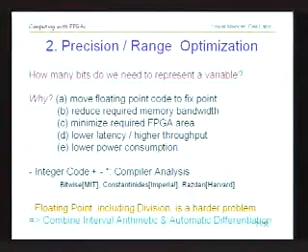The advantages of why we're trying to do this are basically we could convert floating point to fixed point code, which has obvious advantages in execution speed. We reduce memory bandwidth because we are now trying to get less data from the memory. We're just getting the data that we actually need. We minimize the area on the FPGA and reduce the latency for these particular applications.